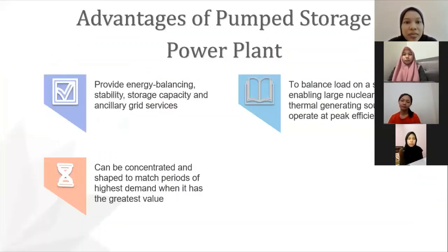Next is the advantage of pump storage power plants. The pump storage power plant provides energy balancing, stability, storage capacity, and auxiliary grid services, such as network frequency control and reserve. This is due to the ability of pump storage plants, like other hydroelectric plants, to respond to potentially large electrical load changes within seconds.